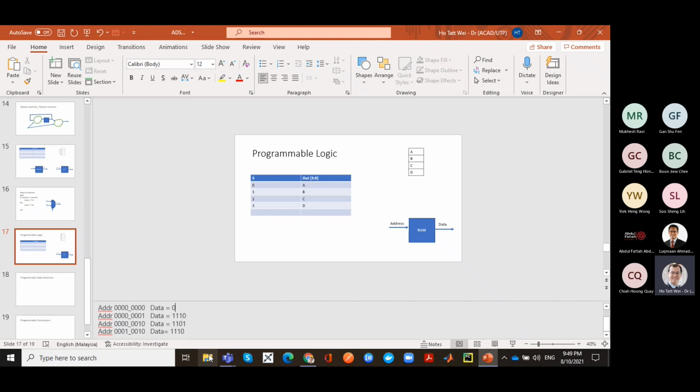So if I reprogram my RAM with these values here, this adder all of a sudden becomes a subtractor, right? And the idea is I can do this in real time, because I can do this while my circuit is running. So the interpretation that a memory can implement a circuit opens us up to the possibility of changing the logic function or the computation of that particular state in our circuit. And this is where we get this idea of programmable logic.